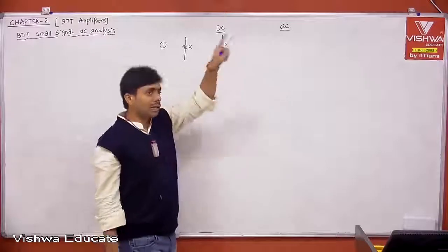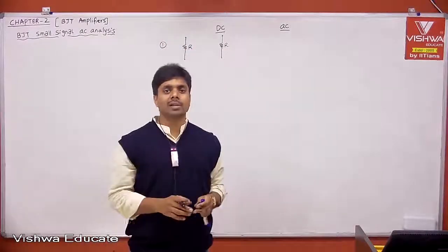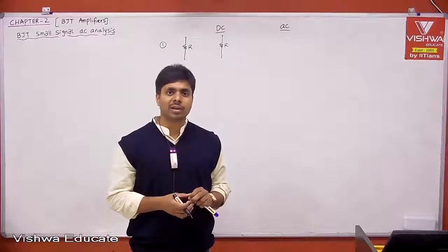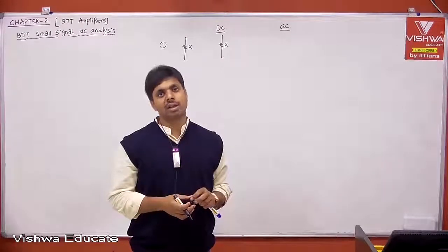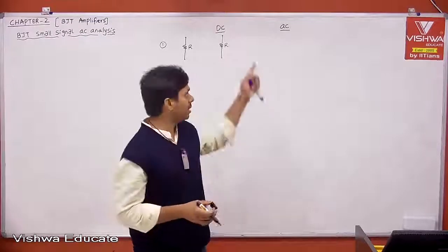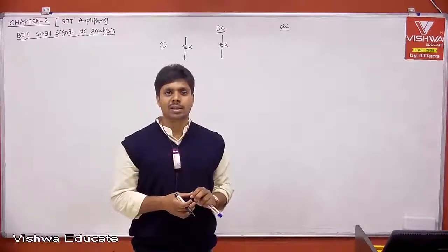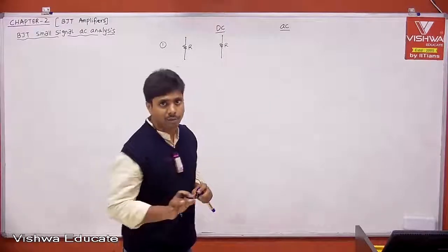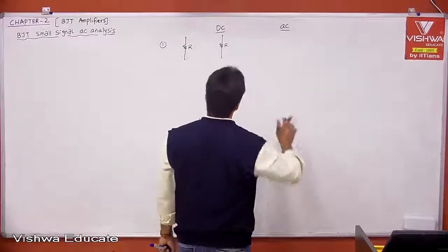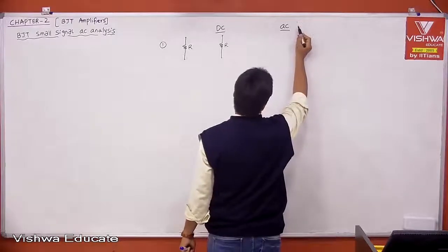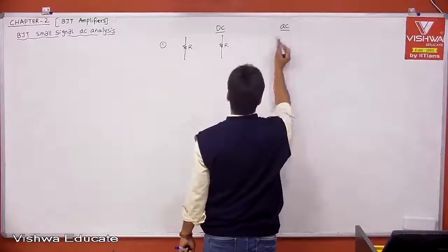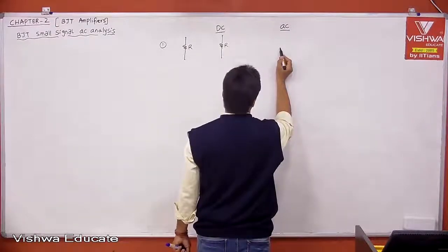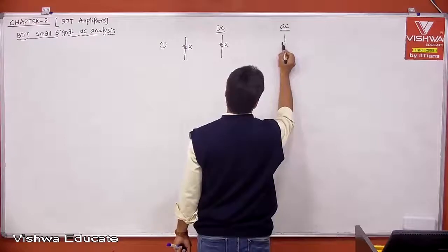But at very high frequency, like hundreds of megahertz, 800 to 900 megahertz, or in the order of gigahertz, because of skin effect the resistance changes. I'm not going to that much frequency. When I say AC frequency or AC analysis, it is less than 100 kilohertz or less than 1 megahertz. Now if you take a resistor, this is a resistor only.